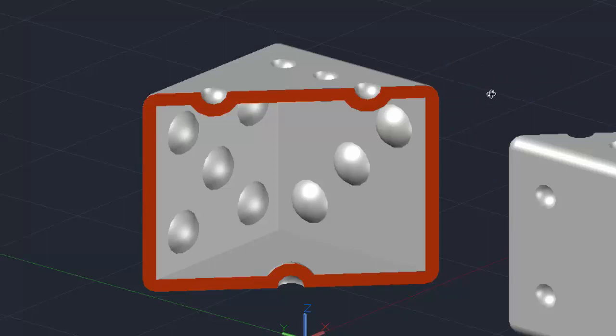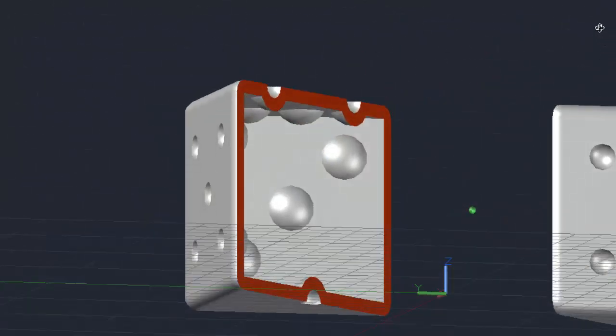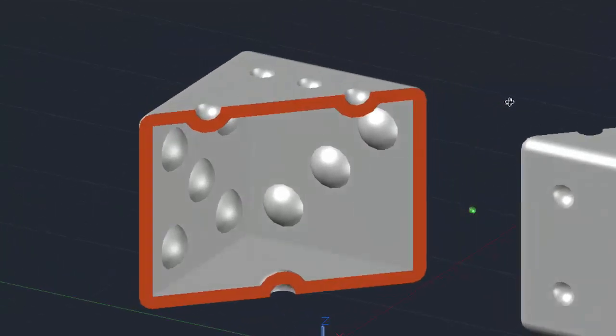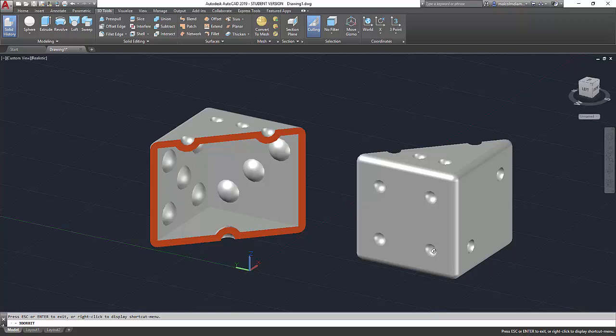If I just hit my orbit command, you can see that I've now got that sectioned and shown that it's a section because it's bright red. I could do the same thing by selecting the dimples. Be very careful though, because it might pick one of these from the other side of a dimple. So maybe going back into wireframe will be a good thing when you get to that point, but you will see the mesh that forms the dimple turn the color you want. That way you'll know whether you got it or not.